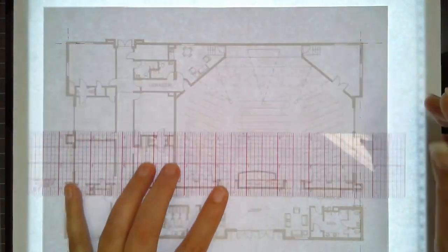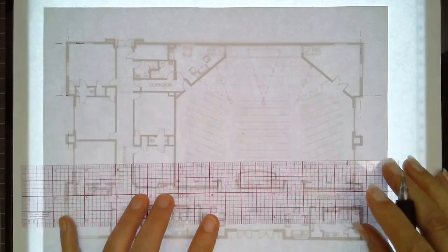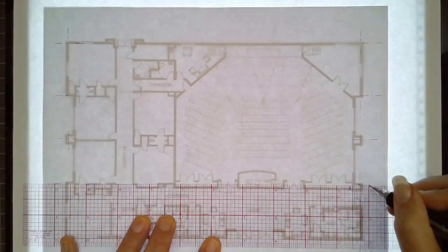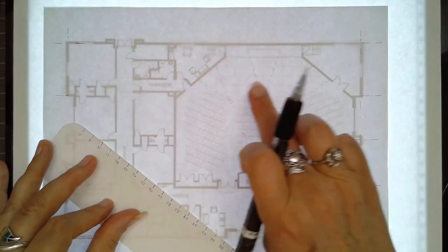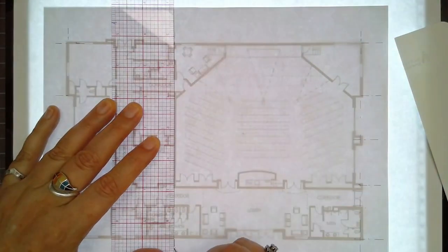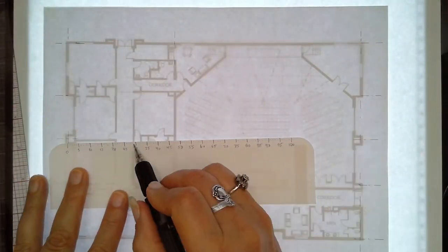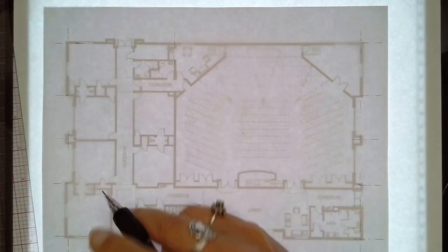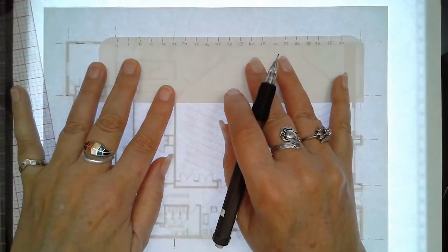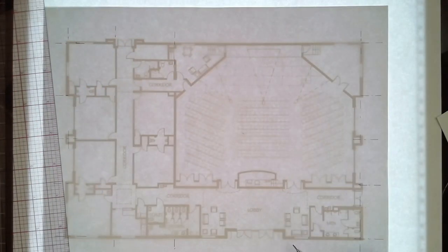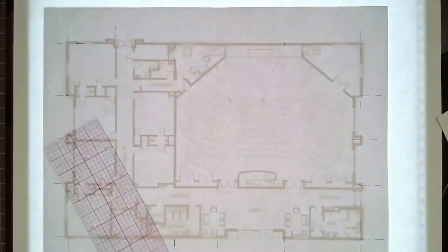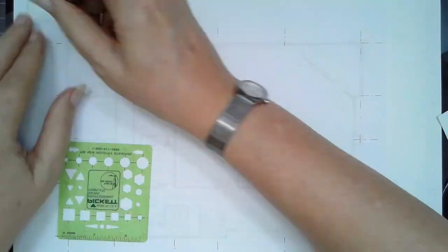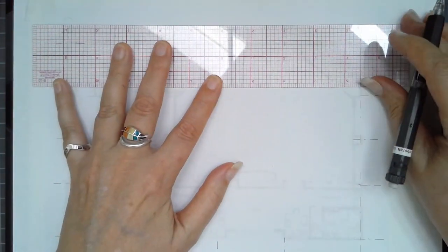So what I'm looking to do is align my column grid with major interior features, interior partition walls, and they're in natural locations in the horizontal direction. In the vertical direction, I want to recognize that there's a large auditorium space. I don't want any columns in it, so I'm going to use the wall that bounds the office areas with this auditorium, and then use the first wall from the inside to make my primary column line. And so I actually have a column line that goes across the corridor on the right. And for the other walls, I want to make sure that those columns do not fall into a window area or something like this.